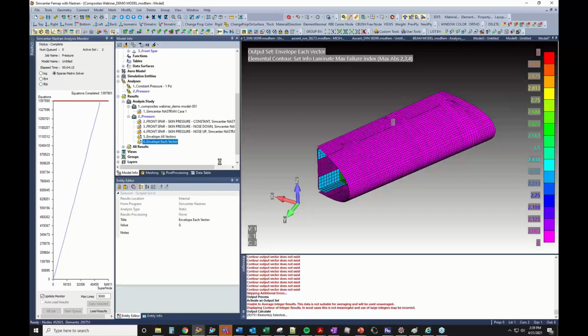So like I was saying before, typically you might just output all that data to the data table and then copy and paste it into Excel and run the calculation. But for something that's easy enough to calculate within Femap, it might be beneficial to use that to create a contour plot within Femap, and now you have a picture that you can put into a report or on some slides, or even just to have the data all in one place, and that kind of keeps it easy. It's still loading. So once it finishes loading, I'll show you what it looks like.